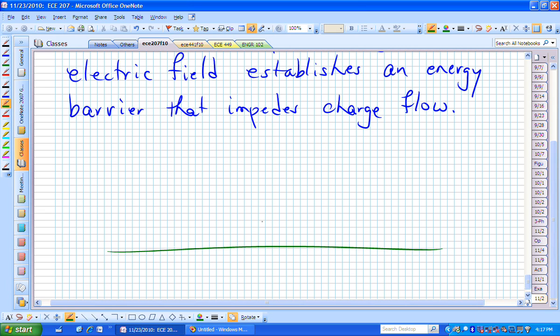Here's what we have then. Remember what behavior we have? Here is our voltage across that diode. Here is our current. And we said that in the forward direction, if we apply a voltage across this diode, which means that we positively bias this diode, it's going to naturally want to start conducting once we get a forward voltage across that diode of about 0.6 volts.